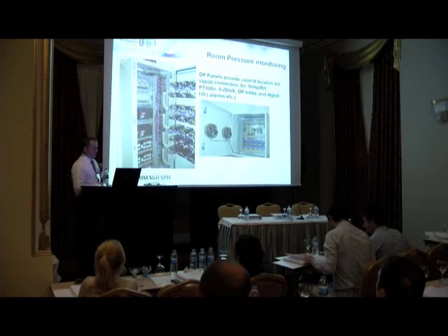In addition, both of these units can drive additional alarm beacon stacks, which you may want, for instance if this is a large area, connected in individual rooms. The alternative to this is that, as we touched on earlier, a PC with a touchscreen in the area. The main advantage with this is it gives the personnel in the clean rooms, if there's an alarm or deviation taking place, the ability to actually acknowledge the alarm in the area. The other thing it gives you the ability to do is actually turn the particle counters on and off.